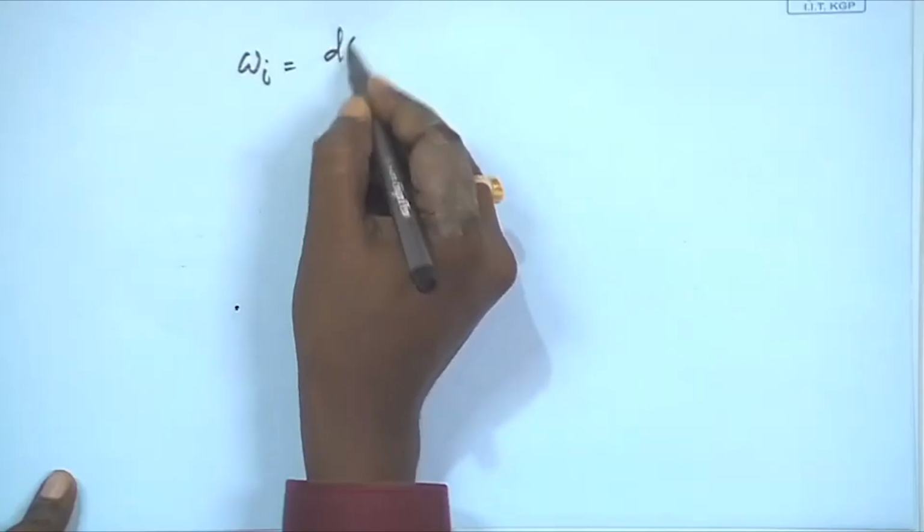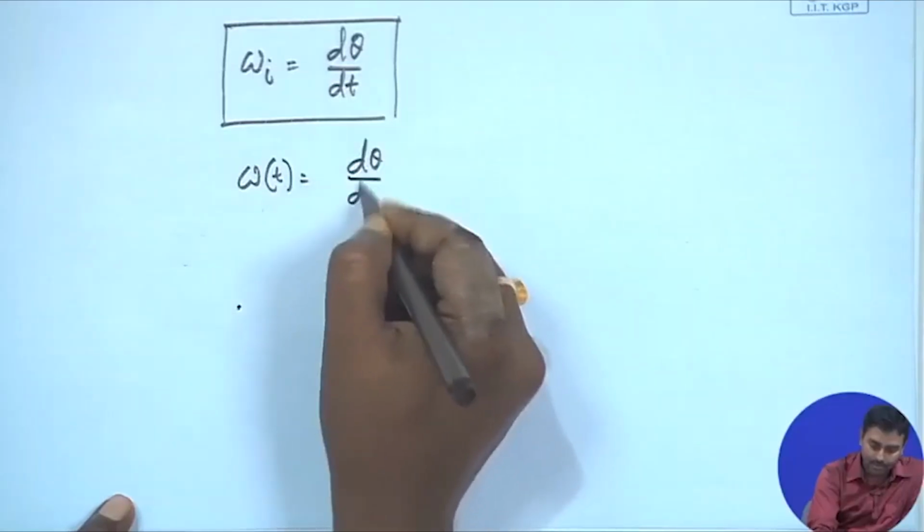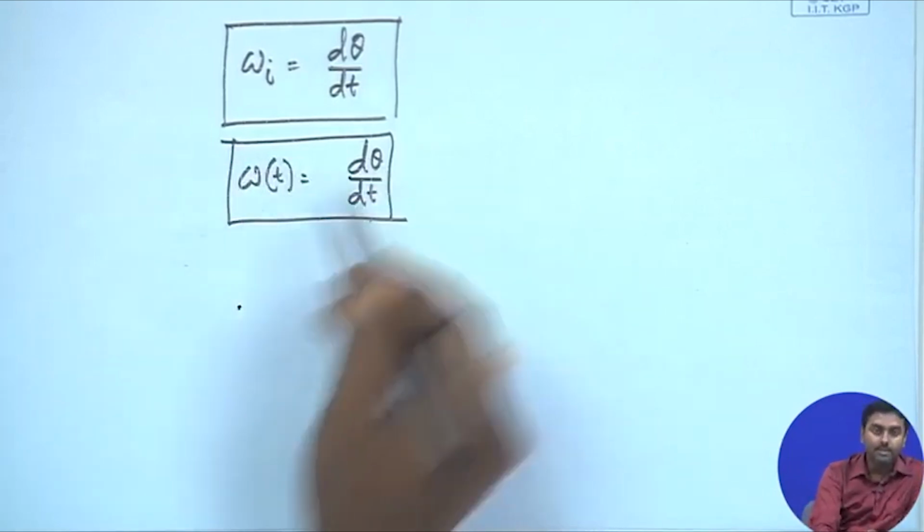It is the rate of change of velocity, and if the velocity varies to any extent, then you define it with respect to the tangent. Now, from differential calculus, we know that the tangent is the differentiation of this particular part. So, immediately we can say this omega i, which is the instantaneous frequency, must be the differentiation of the phase at time t. So, I can always write omega i of t equals d theta by dt. So, a time varying relationship of omega i, which is the differentiation of the overall phase of the cosinusoidal, I can write.